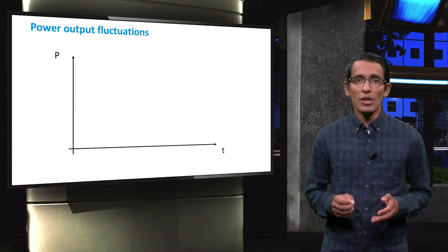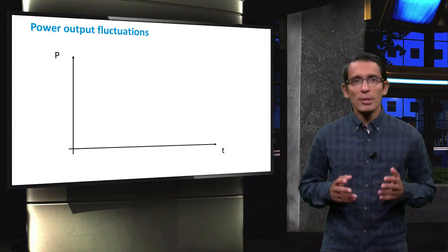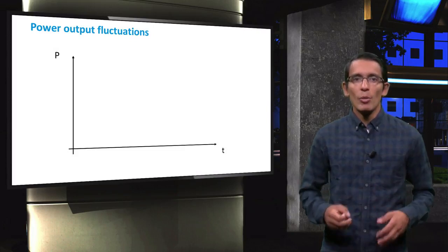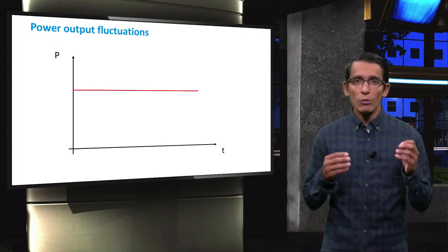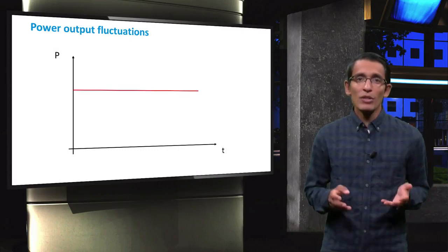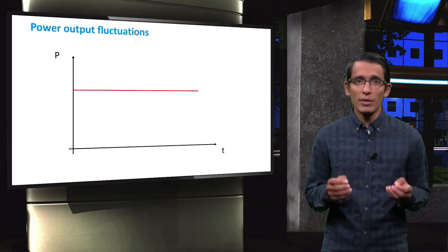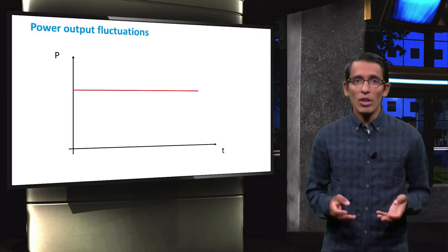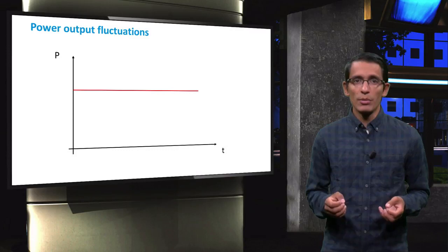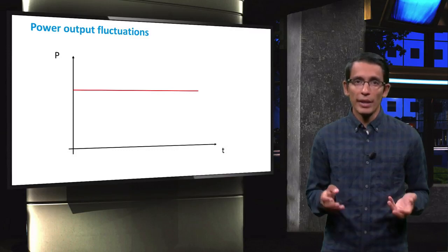Fluctuations in the power output are an inherent problem for distributed generation. This is a problem especially for the utility manager, who must guarantee power to be transmitted to the different loads. In traditional power systems, the power is injected by constantly running power plants into the grid, making management of the power generation according to the system load relatively simple. Now, with widespread diffusion of distributed generation systems, grid management has become more complex.